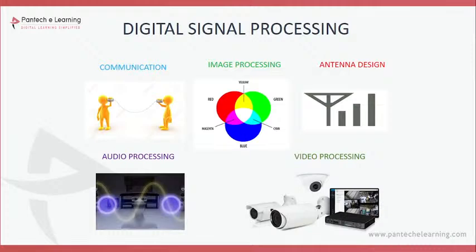One is that the antenna is resonant at the same frequency as the radio signal applied, and the other is that the feed point of the antenna is matched to the impedance of the attached transmitter. So it depends on these two factors only.